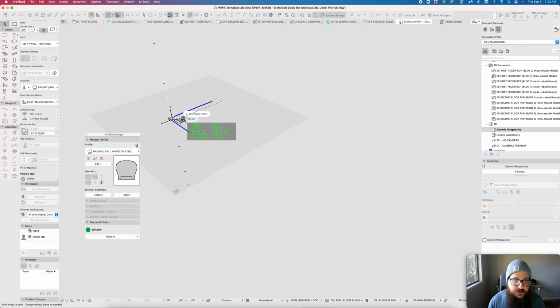You can see even like this under piece right here, how that's coping together and all of the notching in various ways. That tries to find a clean intersection between those two walls. That has caused problems in other projects on really complex curved or large custom profiles applied to walls. So wherever possible, we should avoid applying custom profiles to walls.